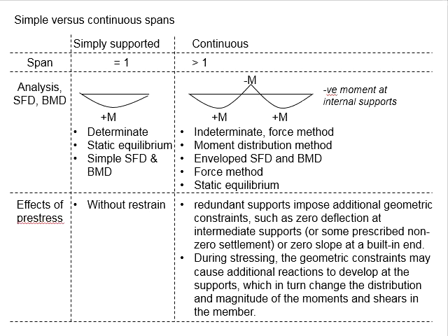You know that the design of the pre-stressing member always starts with the serviceability limit state. Under such circumstances, you will use the factor of safety of 1.0. Then when you come to the design of the moment and shear and even torsion, those are classified under the ultimate limit state. Then you will have the factors of safety of 1.35 and 1.5.